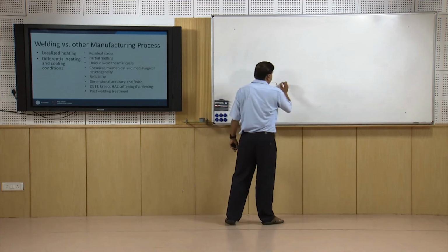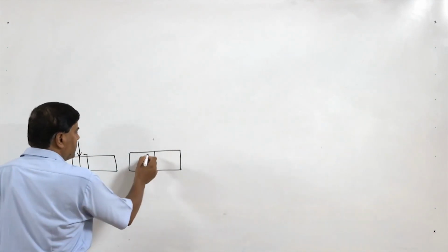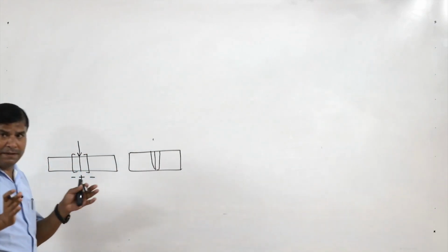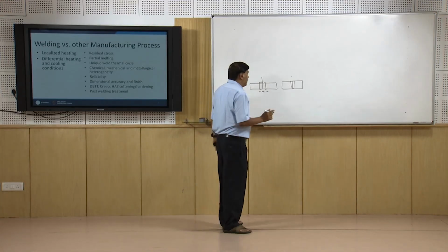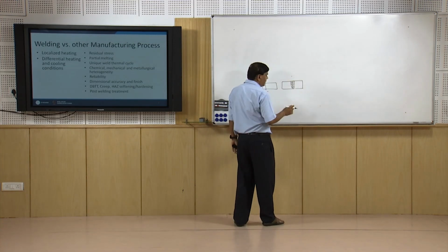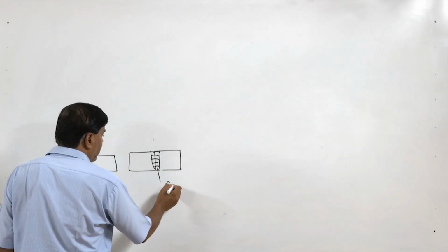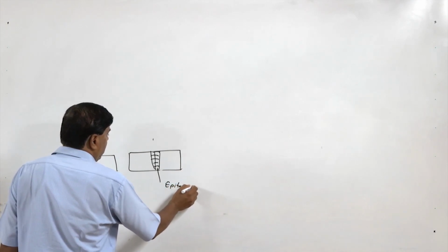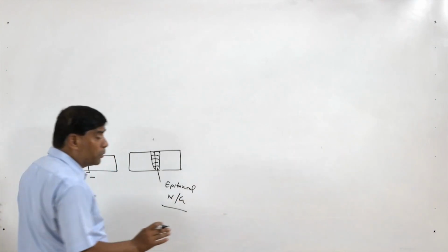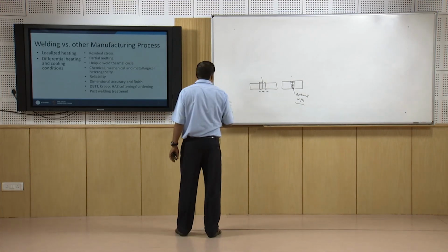In partial melting, we know that welding is unique in the sense that heat is applied at the faying surfaces. So, just partial melting takes place at the faying surface while the rest of the base metal remains in the solid state. Because of this, depending upon the kind of weld metal, whether it is autogenous or a filler of different composition is used, we can have epitaxial solidification or solidification through the nucleation and growth mechanism. So, not complete melting, but partial melting is involved.